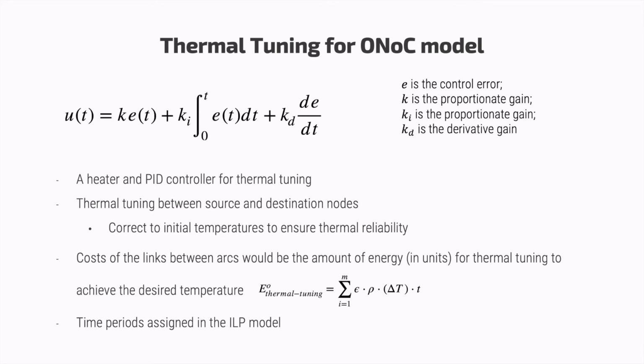As previously mentioned, microring resonators are highly susceptible to temperature fluctuations, so there is a need to maintain a fixed temperature around each MR. A current is applied to a heater which generates heat, which is used to tune the surrounding temperature of the MR. In conjunction with the heater, a PID controller is used for thermal tuning. Temperature data is collected from a thermal sensor integrated with the core, and the corresponding current is generated for the heater.